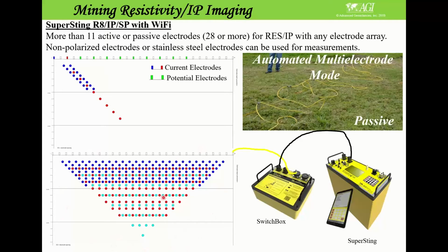And in this case, you can see here the blue colors, like 8 levels, and each color shows a different level. We also have a method we call extended dipole, which is very good for this kind of resistivity and IP investigation, because sometimes channel or level 8 and 7 become noisy in the measurement, because as you go farther away, the signal becomes weak. Sometimes you may get noisy data when you go down to the last levels generally.